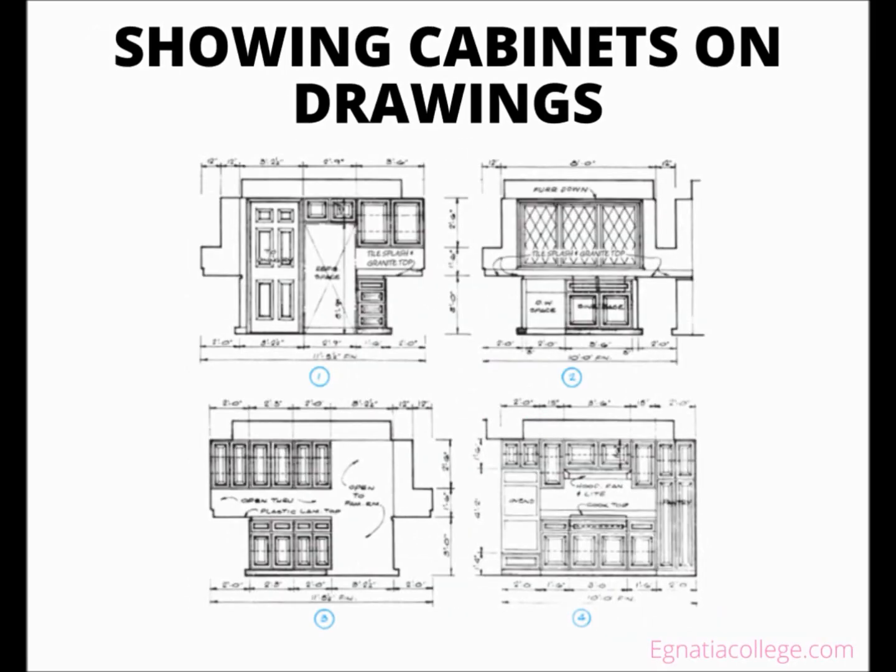When the building has separate electrical drawings, the electrical installer must coordinate these designated outlet locations between the electrical and architectural drawings. There may be electrical outlets shown on the architectural drawings and not shown on the electrical drawings. These variances must be resolved early in the rough-in stage of construction. More complete cabinet information is usually shown on the cabinet elevations.